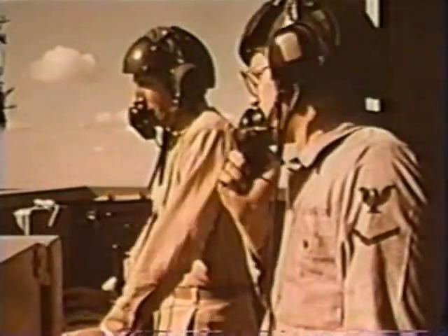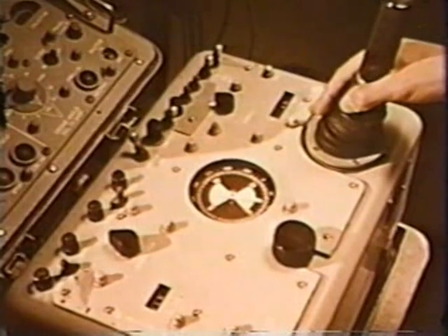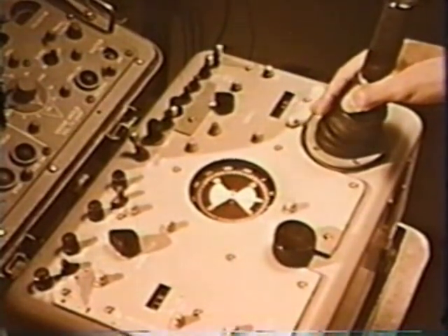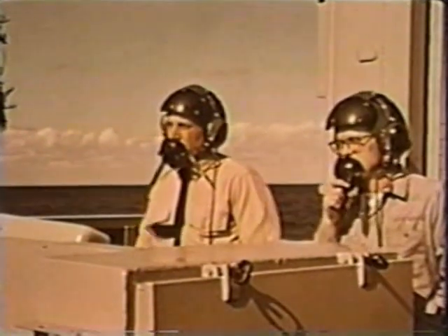When the drone is within 150 feet of the ship, its airspeed is adjusted so that it will maintain its position relative to the ship, while permission to land is obtained from the bridge. The maneuver stick is set parallel to the heading pointer and is deflected in an amount appropriate to the commanded airspeed. Going to maneuver, reducing altitude.